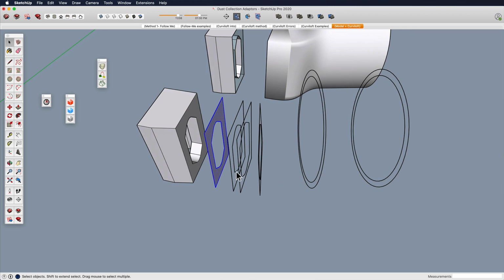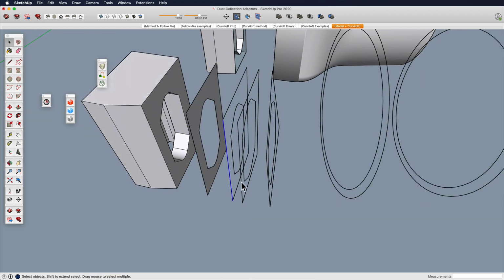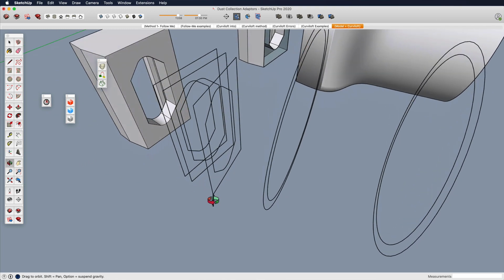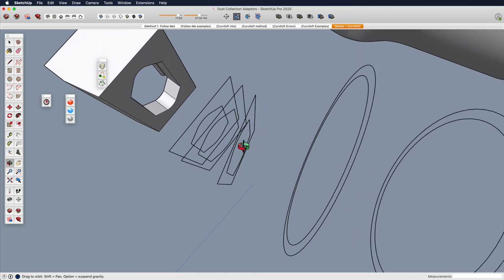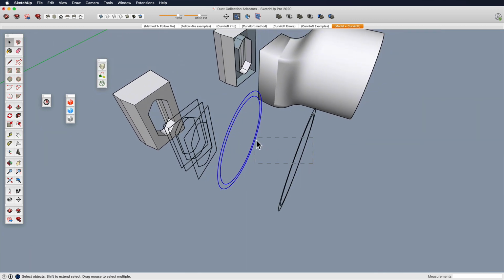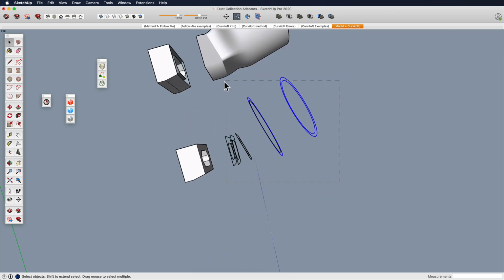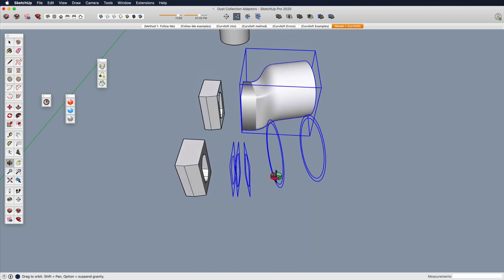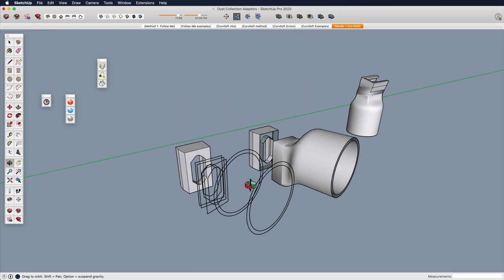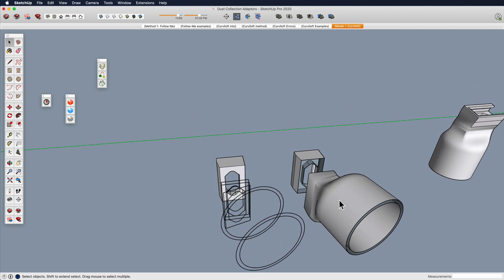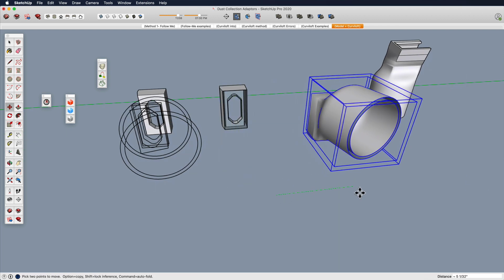And then with that, which is this piece here, you see I took that, I expanded it a little bit, and I scaled the center up, and then I twisted a piece a little bit, and then I've got my hose here. And with those pieces, I could then use Curviloft on the outer and inner shapes of those. This was definitely a case where it had to go through the spline methods, and I had to reconnect a few points to make it work. But that gave me this result.